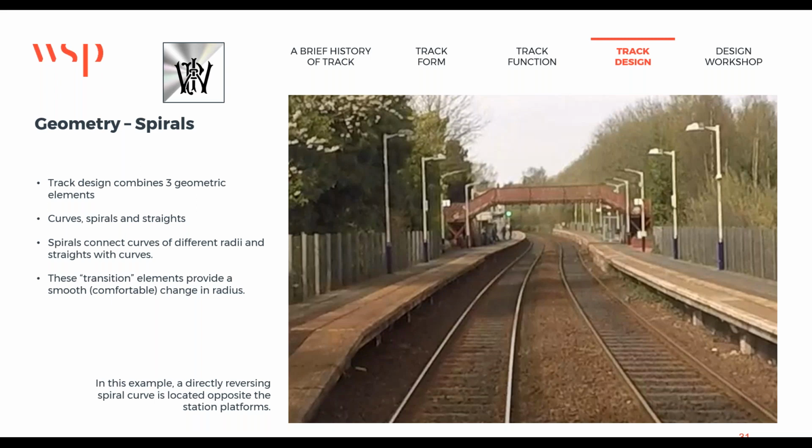Well, there are some benefits. One is in train preparation. And the answer is that train dispatch is much easier since the whole train can be viewed from a single point, and passengers can be confirmed as being on board or about to join. So train dispatch is made a bit easier, but there's always a downside, and the disbenefit of that reverse curve at that station platform is in the maintenance of it.